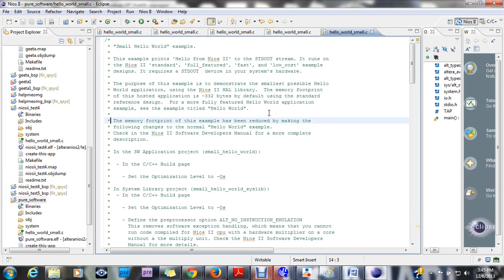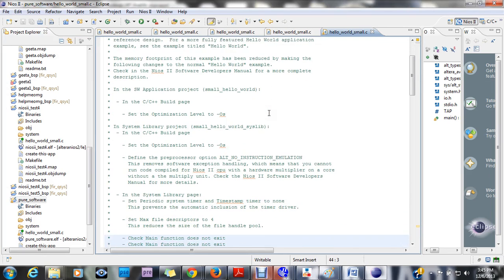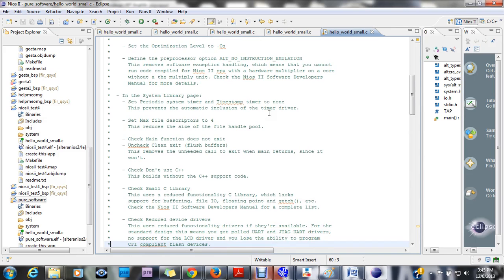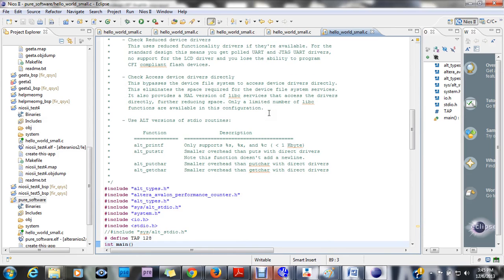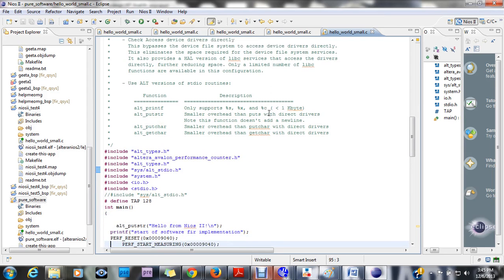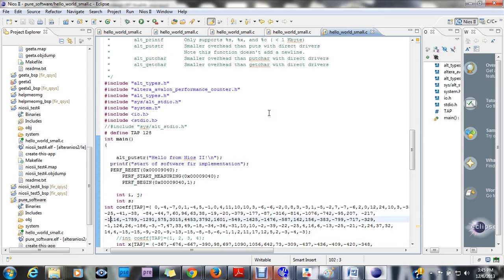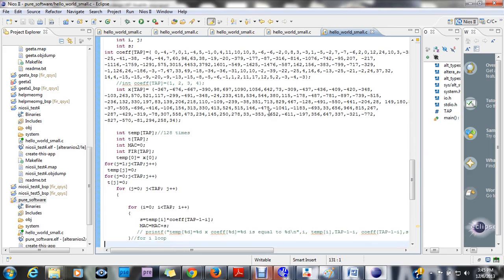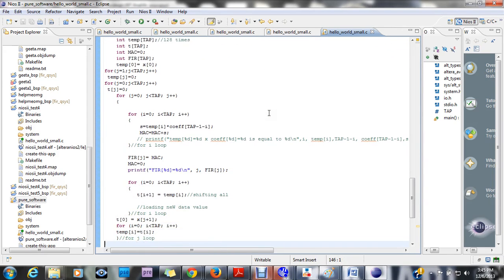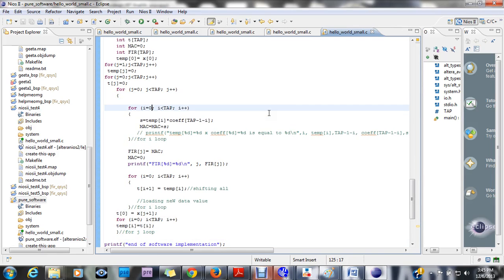The hello world small template has been used because it takes less memory for all its instructions to be mapped into assembly and stored on chip. Otherwise, if the custom template is used, it throws a memory insufficient error. This C code has been developed by me, in such a way that it has multiple memory accesses. Everywhere it has a for loop within a for loop, so it has like 128 times 128 memory accesses, which deteriorates the performance in a very bad way.